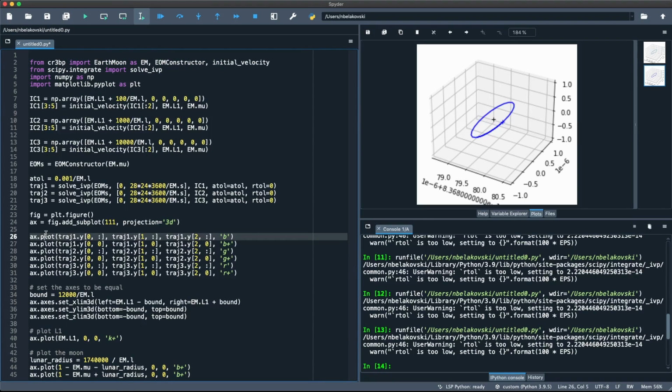We're going to integrate for an entire year, and we're going to make our maximum step size 1 day, so that we have an opportunity to do a maneuver at least once a day. And then we'll sum up all of our maneuvers and see how much delta v that cost. To do that, we're going to need to break the integration up.